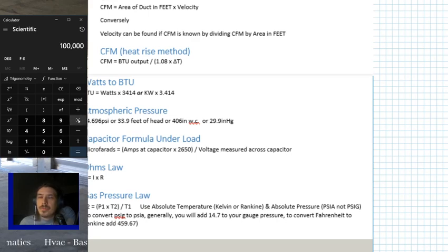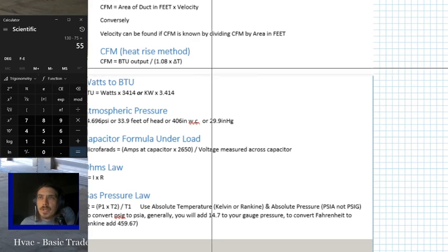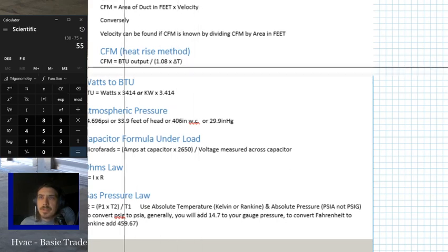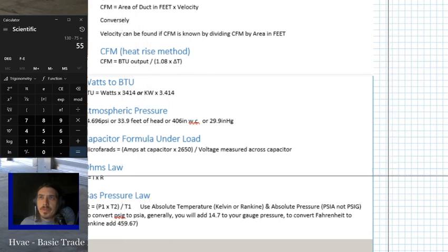As another example, you had a 100,000 BTU furnace. So 100,000 BTU, 90%. So let's say times 0.9, 90%, 100,000 BTU furnace would be 90,000 BTUs output. If we had 75 on the return and 130 on the supply, 130 on the supply minus our 75 on the return gives us a 55-degree delta T. So we've got most of our numbers now, right? We got a 55-degree delta T. We got a 90,000 BTU output.